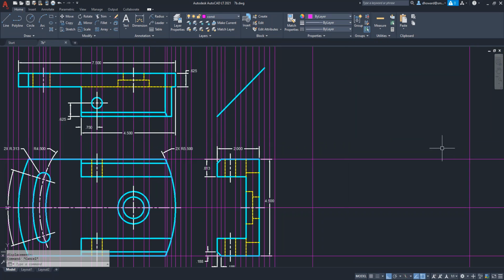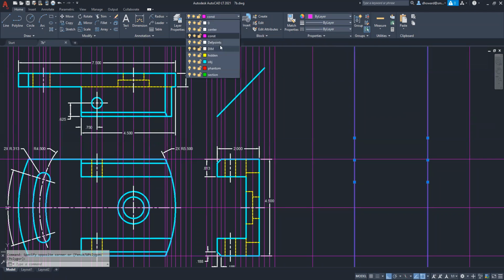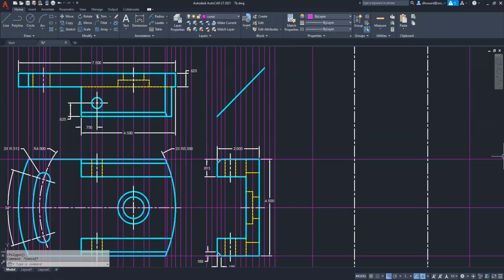The next really defining characteristic is these arcing sides. And we are given their radius as 5.5, which means from the edge where the arc makes contact, it's 5.5 inches over to the center. So if we offset that distance, 5.5 on both, you get the center of the arcs. So these are the arc center lines right here. If you use some pretty basic math, you can also figure out that those happen to be 2 inches over from the edge. So you could just offset the edges 2 inches if you'd rather.